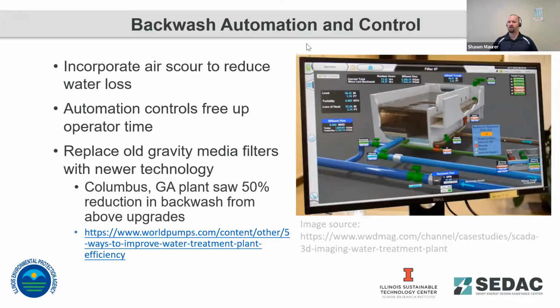As it builds up over time, you get an initial increase in filtration capacity as more materials start blocking the passage of particulates through the filter. But eventually, as it gets loaded, you start getting breakthroughs. Some materials get forced through by the pressure, and you start seeing an increase again in that turbidity. And that's when a sensor would trigger a backwash cycle for a system. So there's a couple different ways to look at how to control backwash water, minimize the consumption of water during the backwash process, and minimize how many times per day you're doing a backwash cycle.